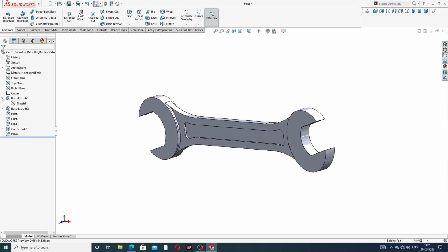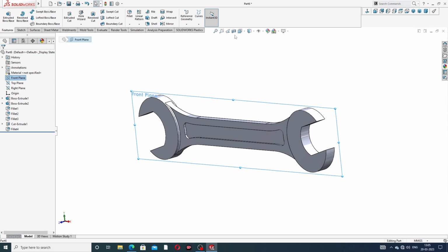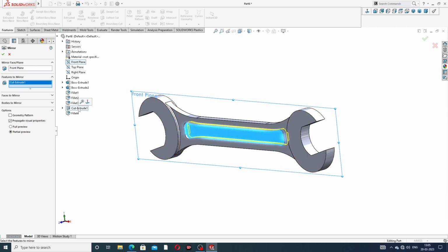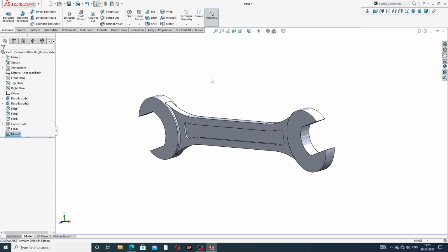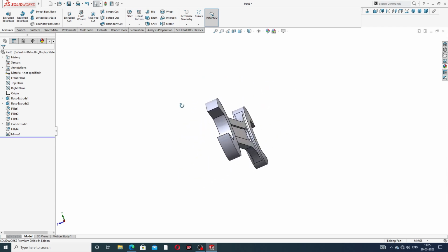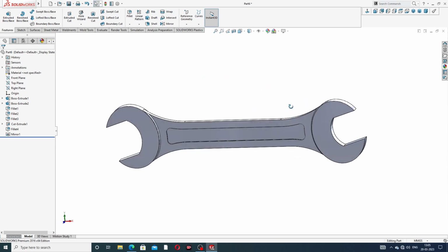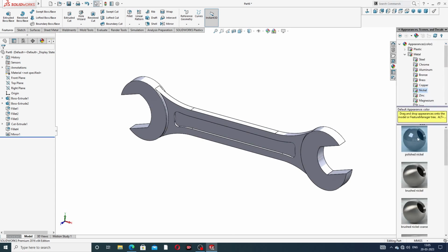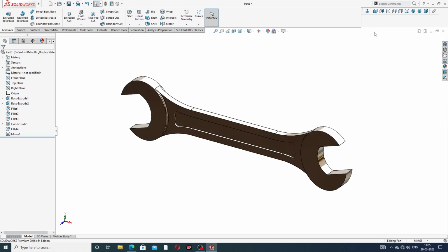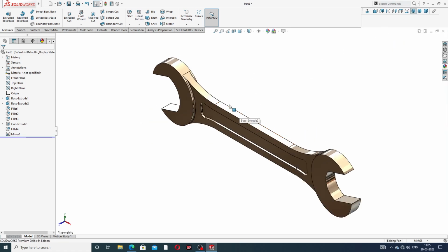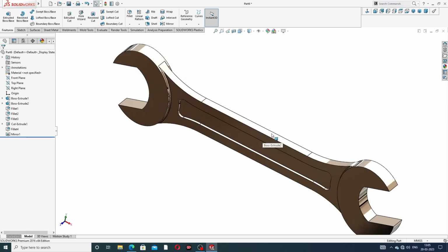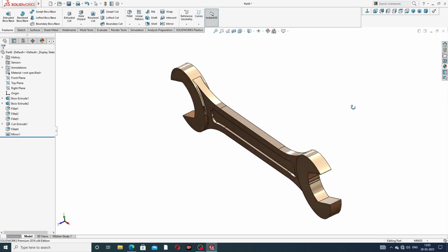And again select this front plane, because this is a mirror. Use this cutout and press the control button and this, click OK. Both sides are mirrored, perfect. Okay, all is looking perfect, and apply material. Material is nickel. And isometric view, perfect, and this body is drawn here.